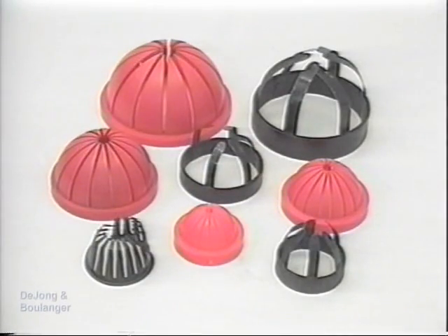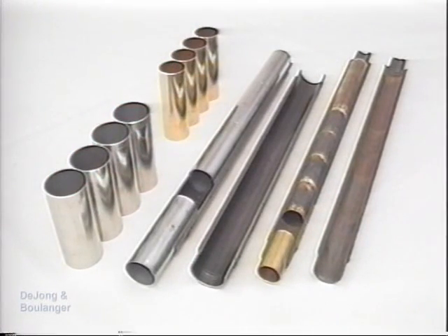If there is any difficulty recovering a full sample, the split spoon may be fitted with a wire or plastic core catcher. In order to better preserve the samples, liners made of either brass, stainless steel, or plastic may be inserted into some split-spoon samplers.